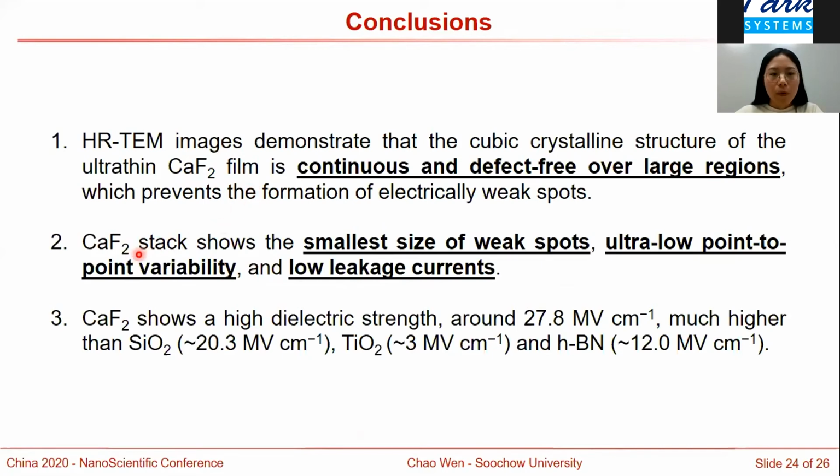Second, our calcium fluoride stack shows the smallest size of weak spots as shown in the current maps, and ultra-low point-to-point variability and low leakage currents, as confirmed in the IV curves of calcium fluoride. Third, our calcium fluoride shows a high dielectric strength, much larger than silicon dioxide, titanium dioxide, and hexagonal boron nitride.